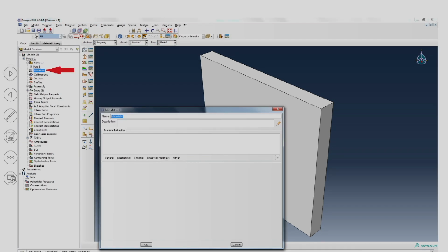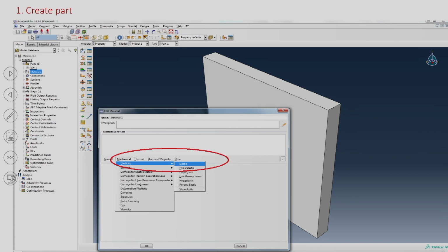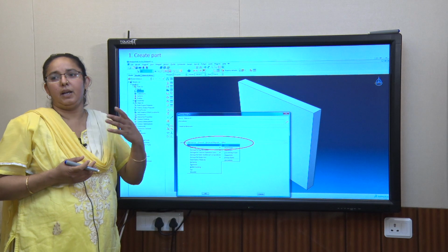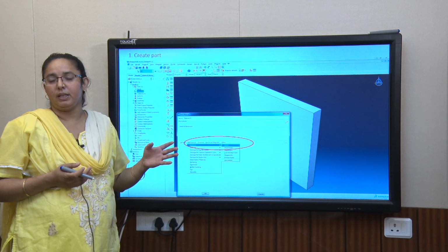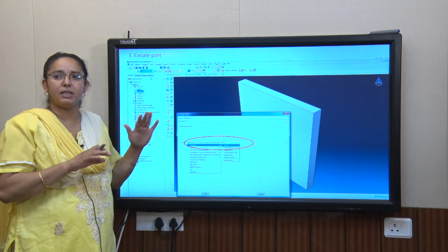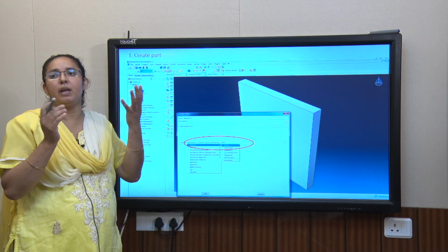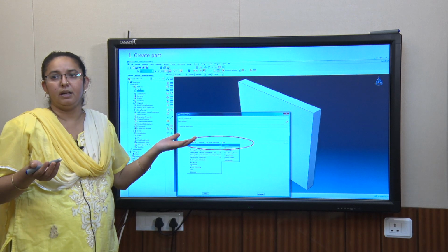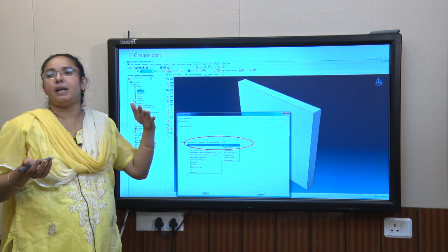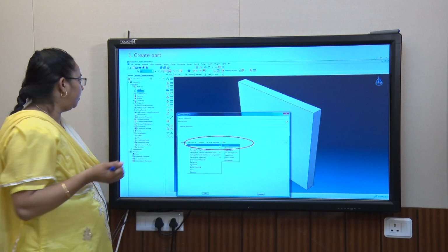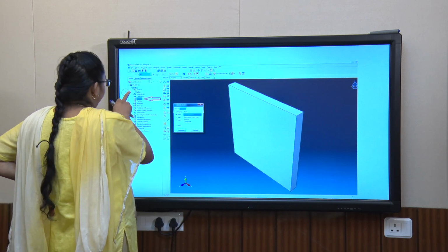In the next step you have to go to the material section, and there one has to choose elastic material, or hypoelastic material, porous material, you see the damage and so on. There are a number of variations. It depends upon your area, in which area you work, you may use those kinds of things. For the present, in this course I have just explained the basics, how to model an isotropic plate or a composite plate under only static loading. Later on one may try different kinds.